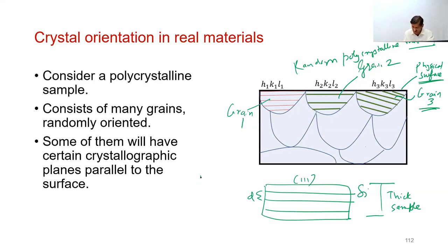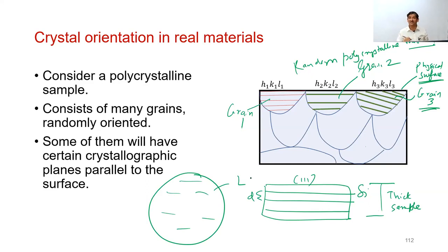So for example, I will draw a figure here. Supposing initially it's a liquid, just imagine. We cool it below its melting point, and supposing the crystals that grow are cubic crystals. I will just draw some simple cubes for you. I will just change the color. So here is one cube, this is grain number 1 or crystal number 1, with its 100. Simultaneously some other crystal might grow in some other direction. This will be 100. There's another growing here, this will be 100. At some point they will start impinging upon each other.